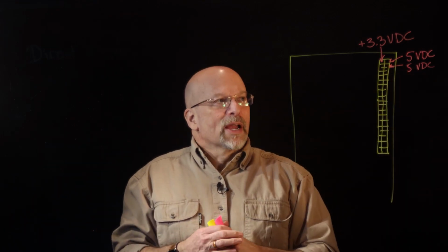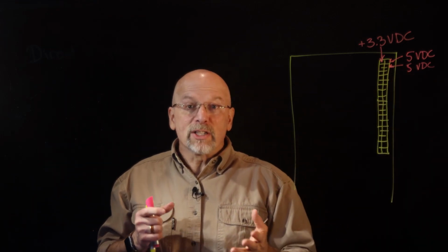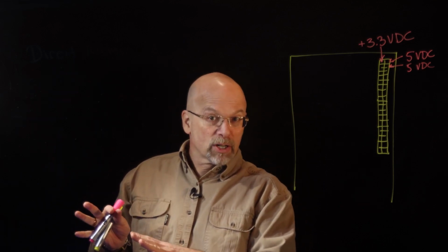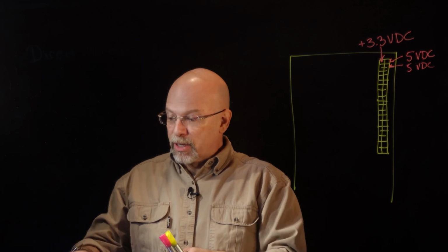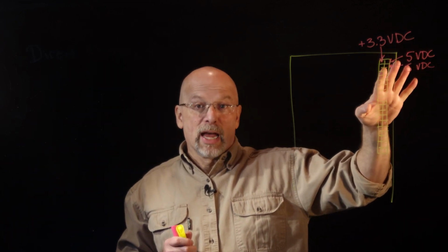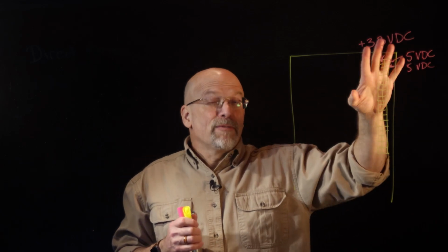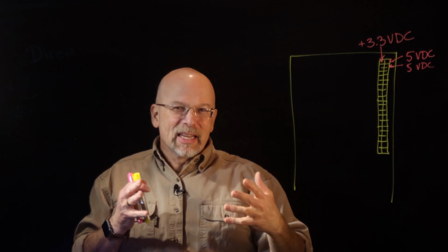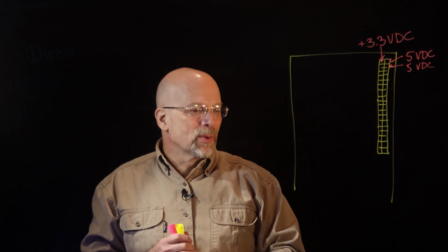That 5 volts right there, in fact, if we were going to use the voltage coming from the USB power supply in order to control these LEDs, we would probably just drive it directly off of those pins. Those are fused, but really not much else. There's not any control, it's just coming directly from the USB port.